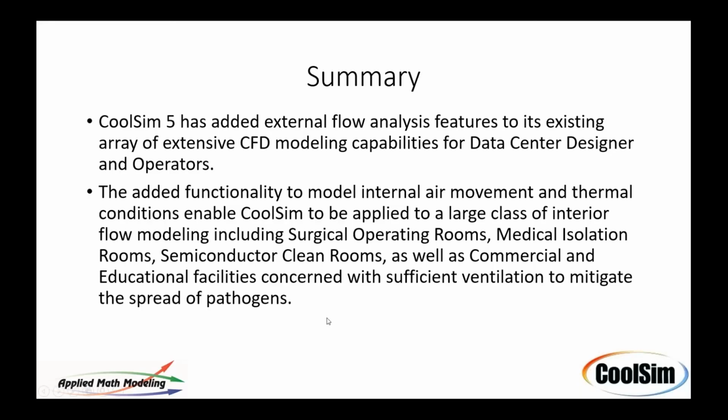So we've added external flow capability to the tool, but we've also done a whole lot more than that. It's going to help you for internal data center design. It's going to also help you extensively for external flow analysis. You can put internal diffusers on walls. You can create structures. You can create unique structures with inlets and outlets. You can do all kinds of unique assemblies with inlets and outlets and set them all to whatever condition you want. If you group them, it'll also report out as a group into the summary report.